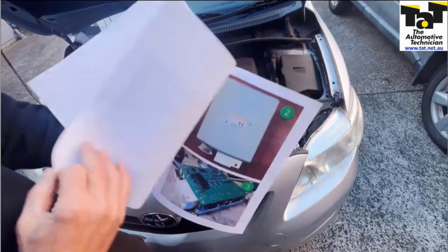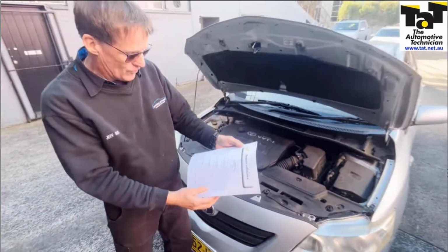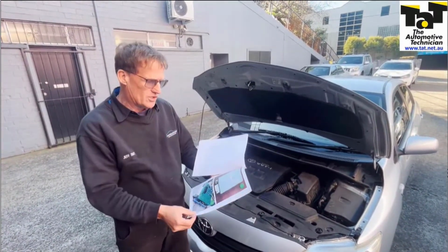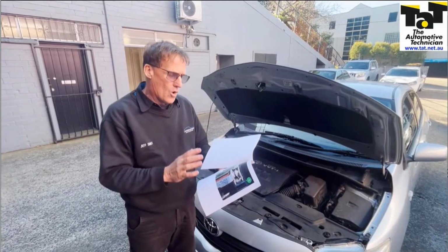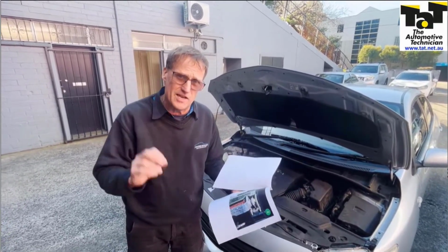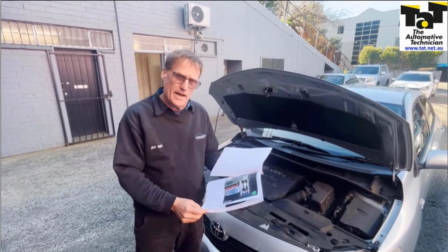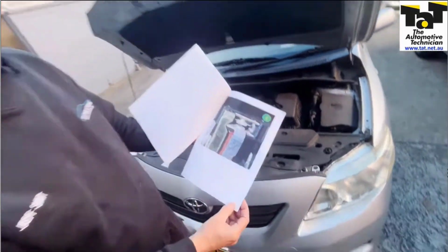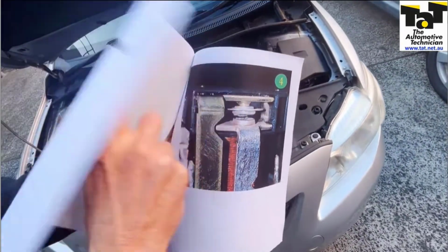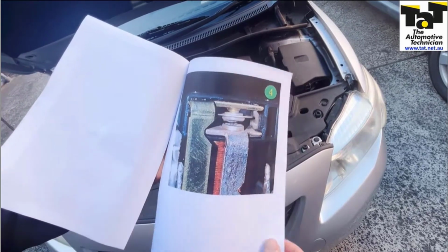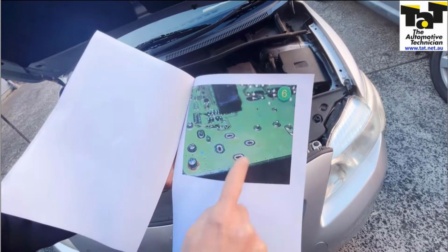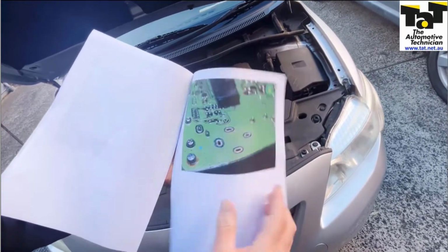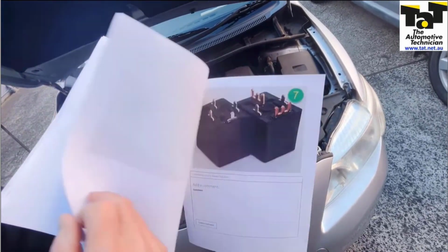And again, the common issues with these are they're coming up with fault codes for different modules, but it's actually inside the printed circuit board. So you can replace it with a new module, or you can go around now and actually replace the relays inside the control module. You can see inside here with some of these we had the pitting of the points inside the relays. There's two relays located inside this particular module, and they're the parts that fail. So you can desolder them as we've done here on the printed circuit board, and then mount up new relays which are available.